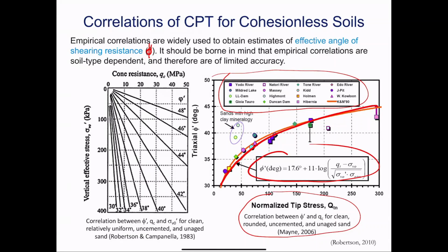Now, the key thing to understand is to make sure that this is relevant for your geotechnical setting, soil type, and mineralogy, and understand that this is very empirical. So don't try to just go into the literature, pull off something, and use it for your project or routine design. Try to use information that's highly relevant for your site, and similar projects done in the vicinity of your project. Then you can take that data, extrapolate it, and get geotechnical correlations for it.